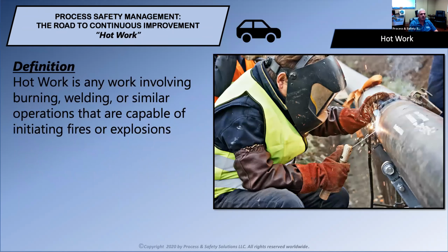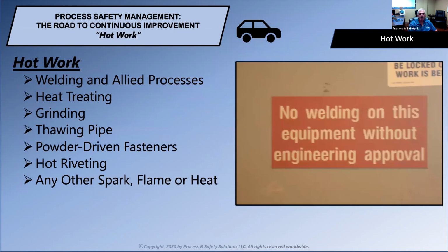So what's the definition of hot work? It's any work involving burning, welding, or similar operations that are capable of initiating fires and explosions. That's the definition in its simplest form. Some of the hot work we see includes welding and any allied processes, heat treating, grinding, thawing the pipe where you have an open flame, and power driven fasteners.